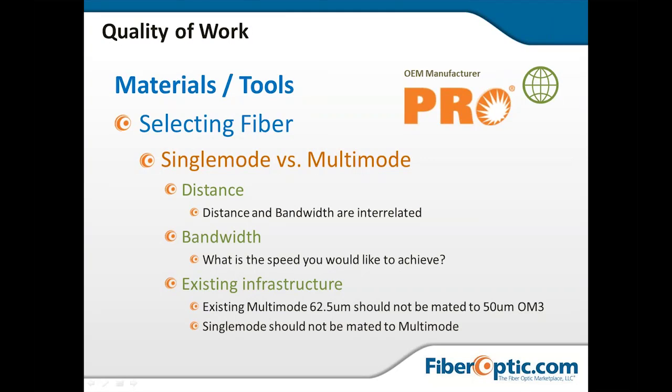It has to do with the way that the actual lasers are manufactured for single mode versus the LEDs that are manufactured for multi-mode. But China and other areas of the world have really only been installing single mode fiber, so the cost of the single mode electronics has come down, and it's pretty much on par, or closer to on par than it was in years past.